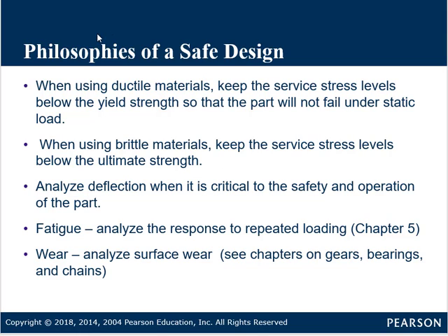So, for a safe design, when we're talking about ductile materials, we want to keep the service stress levels below the yield strength, okay, such that the part will not fail under static load. Now compare that to a brittle material, if you will. The brittle material, we want to keep the service stresses well below the ultimate strength.